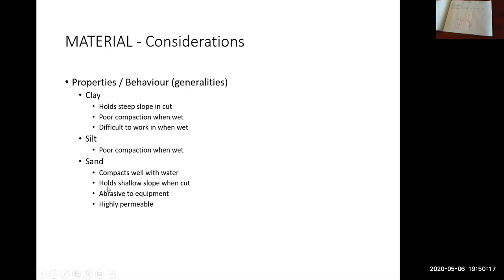So if you were to try to dig a trench in sand, picture yourself out on the beach trying to dig a trench just with your hand or a shovel, and you try to have vertical walls, how long does that stand up before it caves in on itself? Not long at all, right? Probably seconds before it falls in on itself. So you can't dig a trench in sand with vertical walls. You have to be quite shallow, or sloped is another word for that.